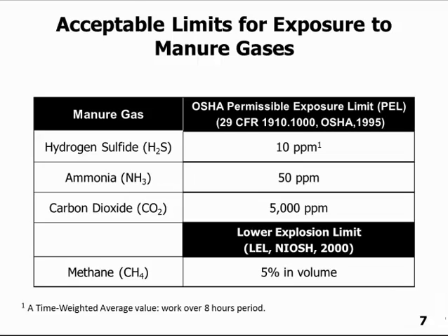OSHA and other agencies, NIOSH in particular, defined acceptable limits for long-term exposure to manure gases. When I talk about long-term, I'm talking about an 8-hour exposure period. For hydrogen sulfide, that would be 10 parts per million. And interestingly enough, recently NIOSH has recommended that that should be as low as 1 part per million.